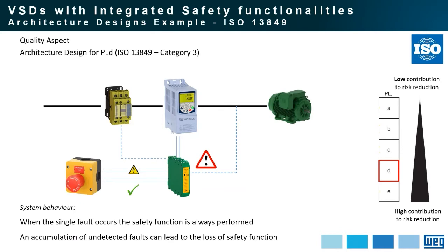In the power line, additional protection must also be considered, because in case of any problem with the variable speed drive, other components must be available to protect and to switch off the motor. So that is the reason to install the safety contactors. If the variable speed drive has a problem, the contactor will switch off the motor safely. And it happens in the other way as well. If the contactor has any problem, the variable speed drive can stop the motor safely.